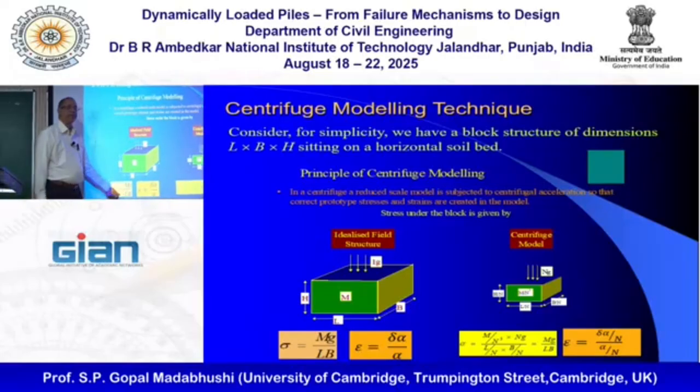As I had here. So although this block is smaller, because the gravity has been increased, it will also apply exactly the same stress. So the soil below this block and below that block will think that they are being subjected to the same stress. Easy, right? Imagine why we couldn't think of this before the lecture. It's so easy, anybody can think of this.